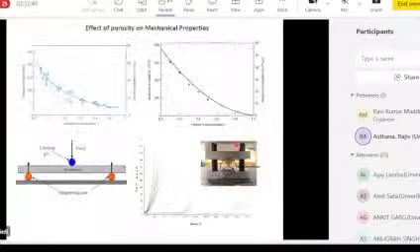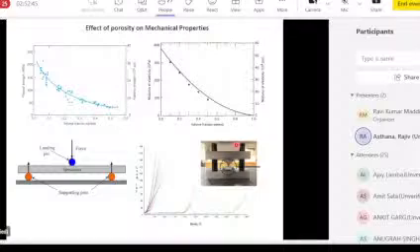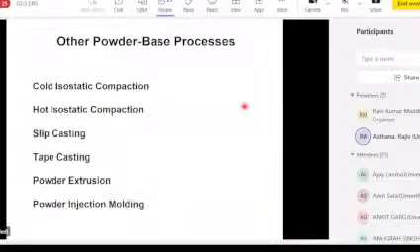And we know that especially for ceramic material, porosity is very harmful. If you have a slight amount of porosity, the flexural strength, the 3-point bend test strength, elastic modulus, all those properties decrease because of porosities. Metals are more forgiving than ceramics, so even with some porosity, the part will not lose as much strength as would the ceramic part.